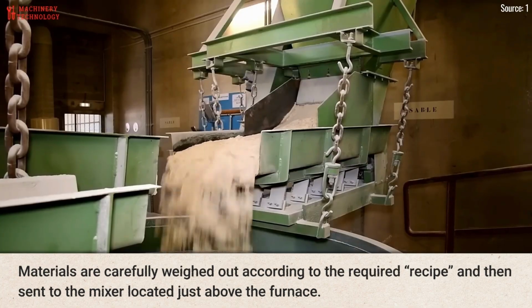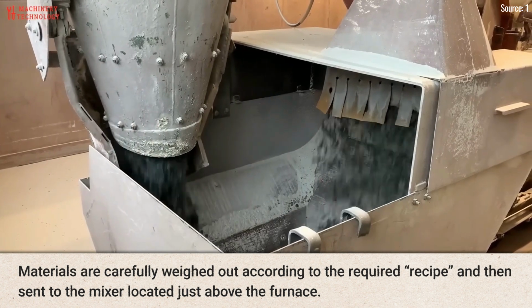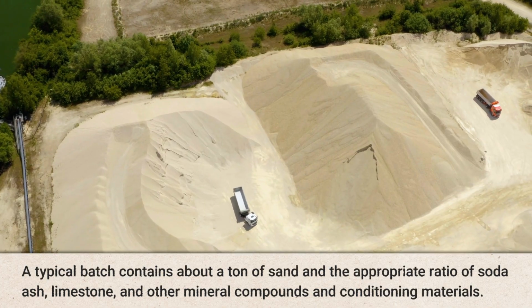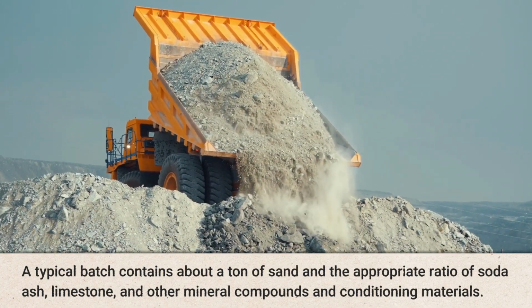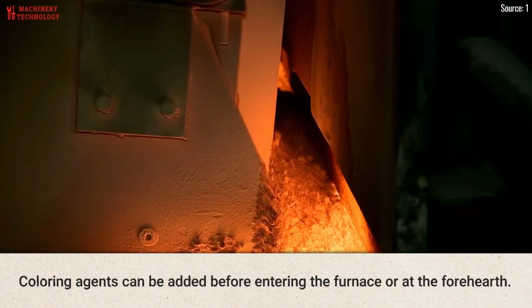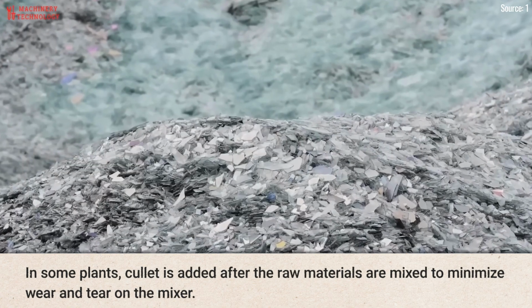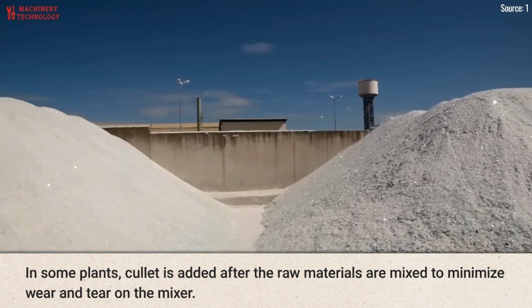Materials are carefully weighed out according to the required recipe and then sent to the mixer, located just above the furnace. A typical batch contains about a ton of sand and the appropriate ratio of soda ash, limestone, and other mineral compounds and conditioning materials. Coloring agents can be added before entering the furnace or at the forehearth. In some plants, cullet is added after the raw materials are mixed to minimize wear and tear on the mixer.